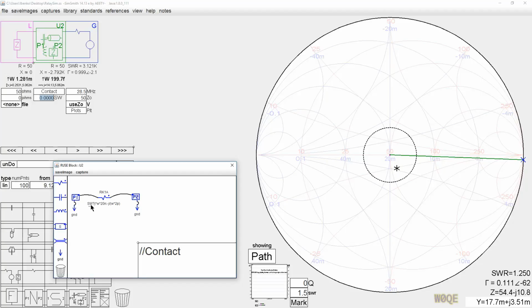I can't make it any larger in here, but it basically says we look at the switch SW for whether the switch is on or off. If it's on, we set it to 20 nanohenry inductance. If it's off, we set it to 2 picofarad capacitance. Whether this is realistic or not, you would have to determine in your circuit, but these are pretty good values. A contact of on is 20 nanohenries and off of 2 picofarads is pretty good.